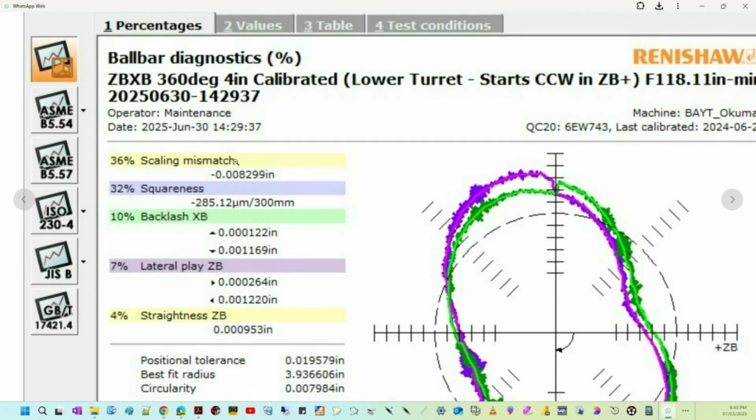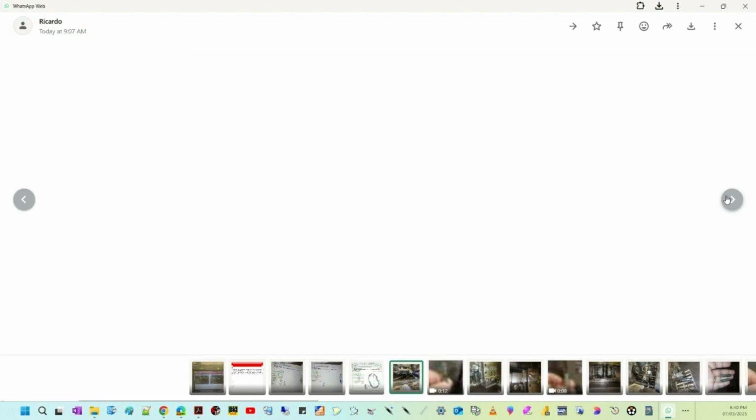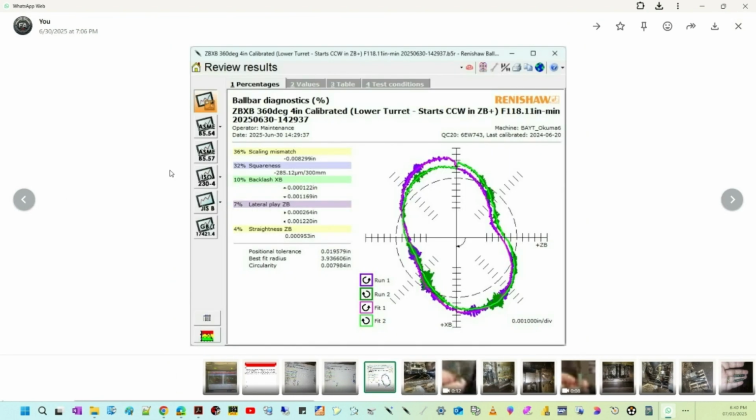It does. But it's surprisingly effective. What you should feel is just consistent, smooth motion. If you feel anything else, weird noises, grinding, any kind of jerky or irregular movement, it tells you something physical is wrong. Like a mechanical binding or something. Exactly. It helps differentiate between, say, an electronic signal glitch and a real physical hang-up in the mechanics.